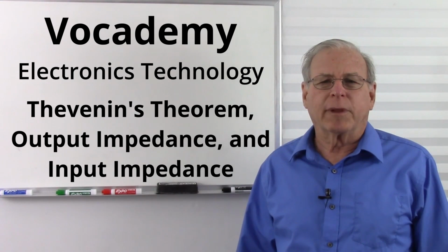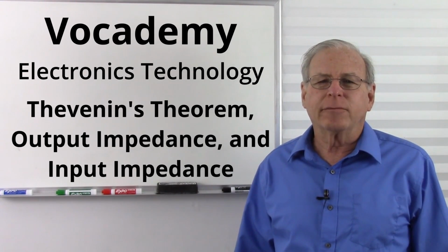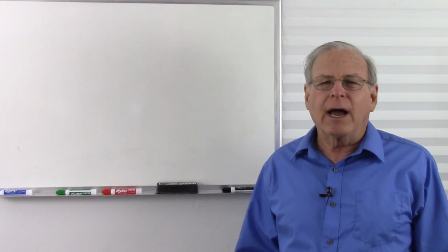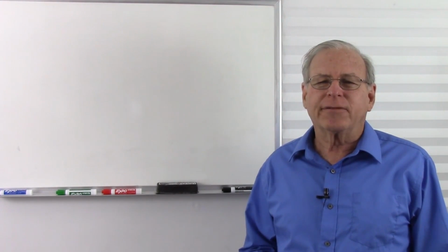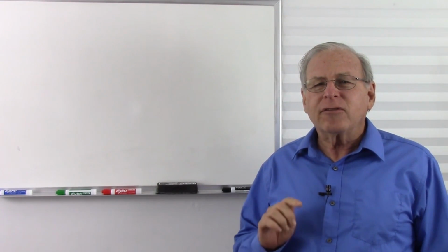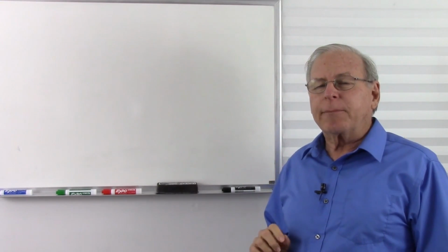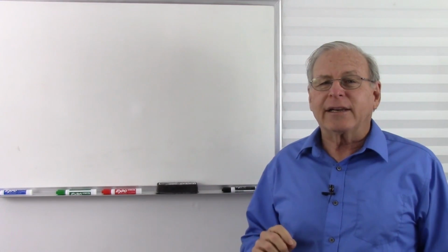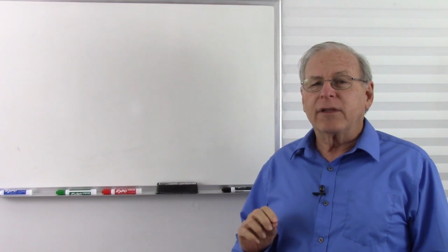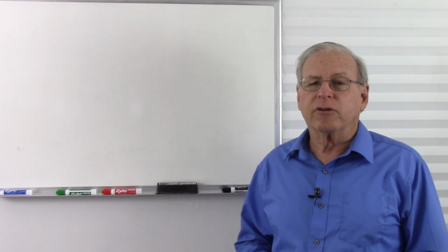Today, I'm going to explain Thevenin's theorem and the interaction between output impedance and input impedance. As I often do, I'm going to express Thevenin's theorem a little differently from what you might see in textbooks, and that is, Thevenin's theorem states that any circuit that produces an output will act exactly like a circuit that has a single voltage source with some impedance in series with that voltage source.